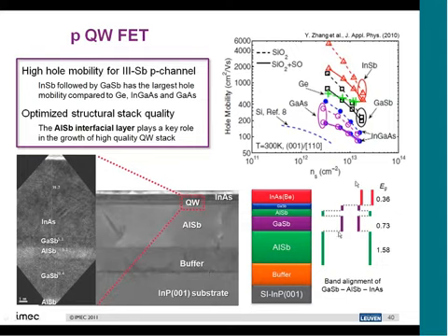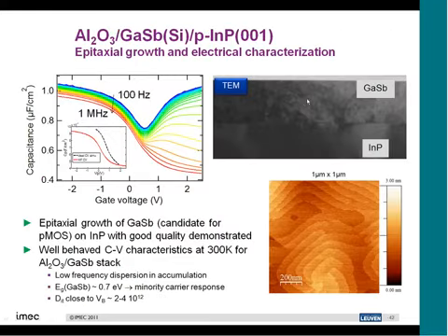This shows the quantum well structure, and we think this kind of structure has lots of promises to use for PMOS devices because it has been demonstrated, at least calculated theoretically, that you can get very high hole mobility with these kind of materials. And these materials actually are very easy to grow, both on indium phosphide. We also have been able to grow them on germanium with very low defect densities, and they seem to be relatively easy to passivate also with aluminum oxide. So this, I think, already gives us an outlook for the next generation kind of devices.